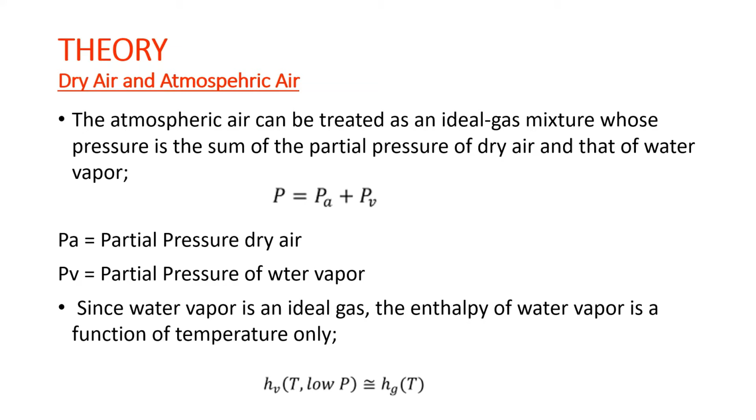Moreover, since water vapor is an ideal gas, the enthalpy of water vapor is a function of temperature only. Therefore, the enthalpy of water vapor in air can be taken to be equal to the enthalpy of saturated vapor at the same temperature.